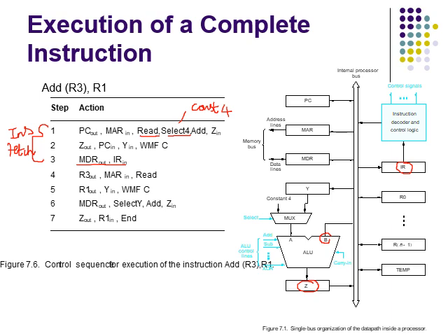The instruction decoding circuit interprets the content of the instruction register at the beginning of step 4. This enables the control circuitry to activate the control signals for step 4 through step 7, which constitute the execution phase.